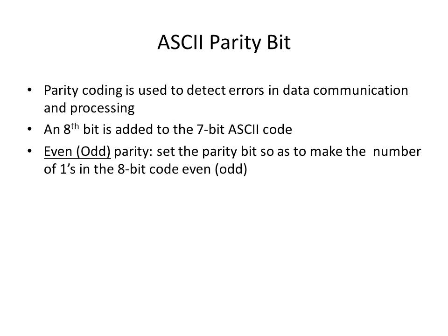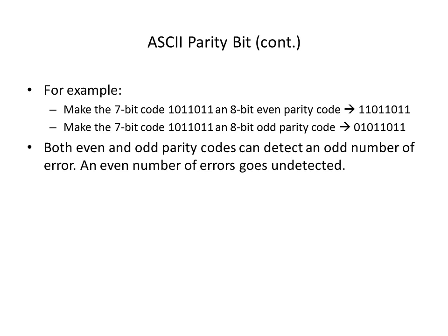In this way, we can generate an ASCII parity bit. In ASCII parity, there is a 7-bit ASCII code and 1 parity bit is added. Here also even and odd parity can be generated. For example, for the 7-bit code 1011101, there are 5 ones already present.